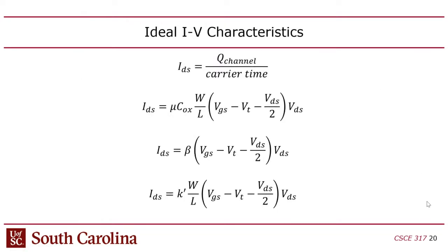Okay, so basically this was supposed to animate. Sorry. If you go back and calculate the whole thing, you have basically two parts of this equation. You've got the gate-to-source voltage minus the threshold voltage, which is basically fixed. That doesn't change with Moore's law. And then the voltage VDS over 2. These are dynamic values that change, except for the threshold, which is a constant.